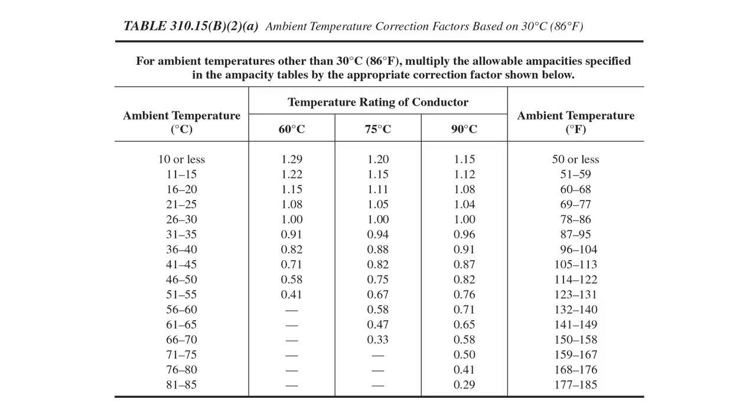So let's talk about another table, 310.15(B)(2). What's important about this table, and what do you want to point out with this one? Well, 310.15(B)(2)(a) is an ambient temperature correction. So if you look at the main table, it says it's based off of 30 degrees C. If you have something other than 30 degrees C, you go to this table and you have to do an adjustment correction.